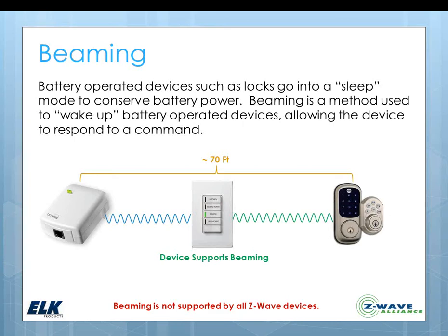So if you're designing Z-Wave networks and you're designing them with devices that require beaming, then the node that's directly communicating with it has to support beaming as well. And again, beaming is simply a newer portion of the Z-Wave protocol that lets us have devices that are battery operated, that can live on batteries for 3 to 5 years, but that can also be reached essentially immediately or virtually without any delay.